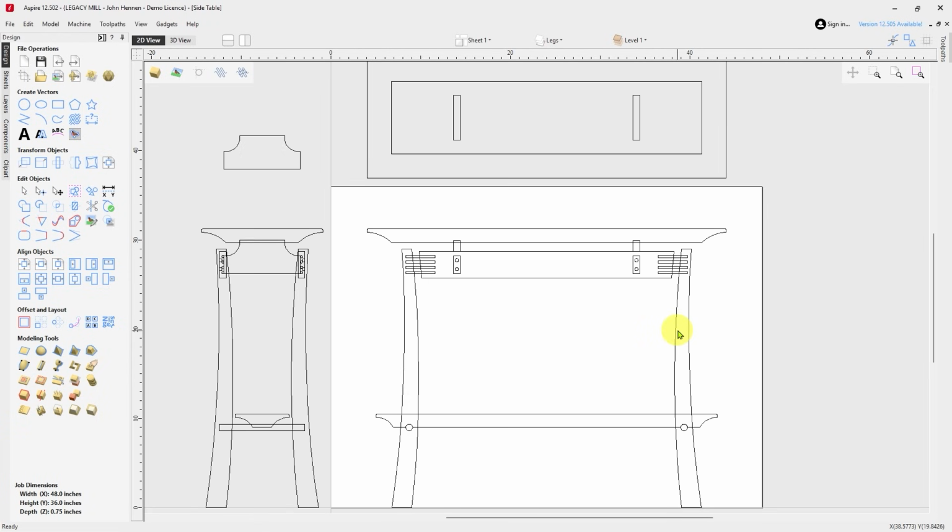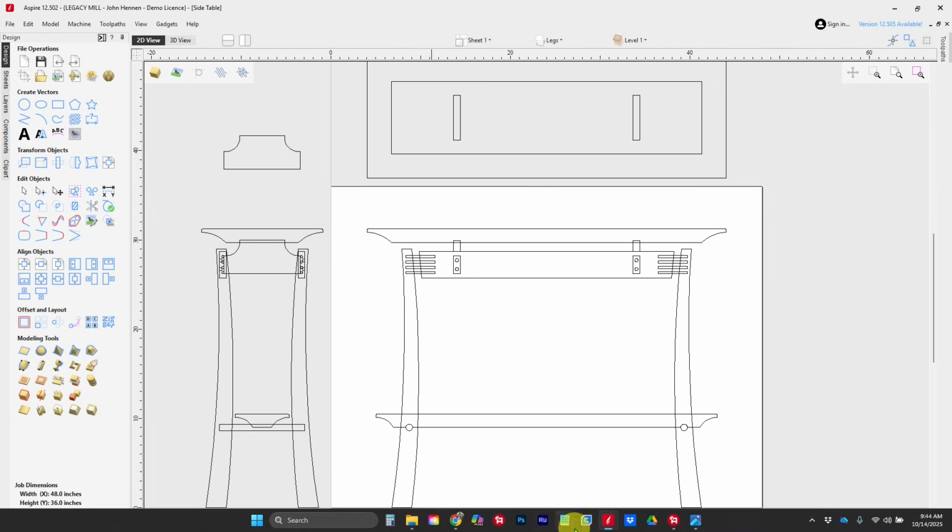Okay, with the skirt machined on both the front and the back side, it's time to work on the end of the board to drill these holes into place. One of the coolest things about the Maverick CNC, the one that I'm using to build this project, is the ability to stand the wood up on its end in its joining system to drill holes down through the end of your board. So here's how we're going to set that up.